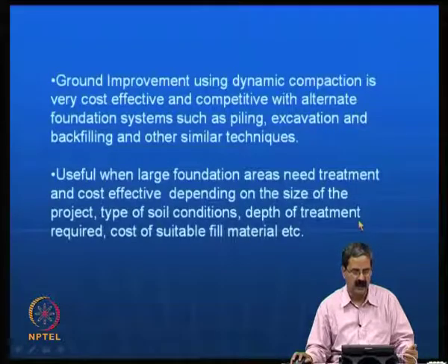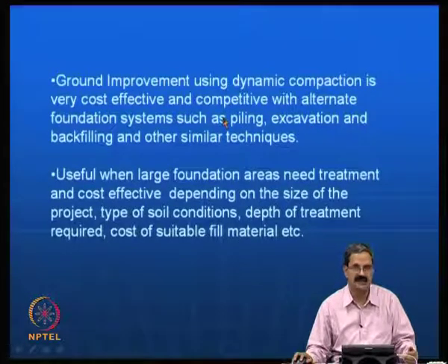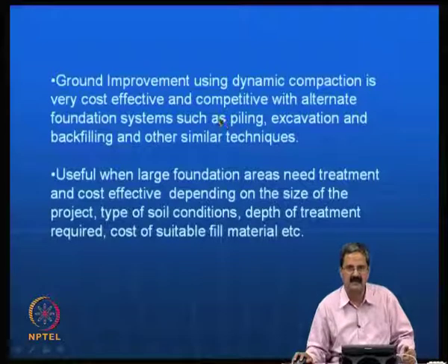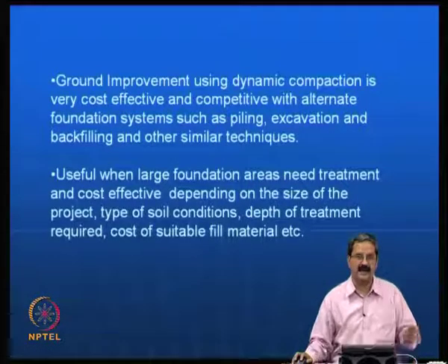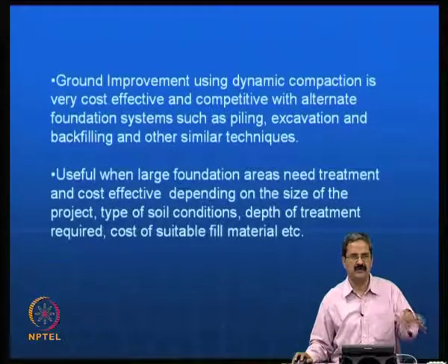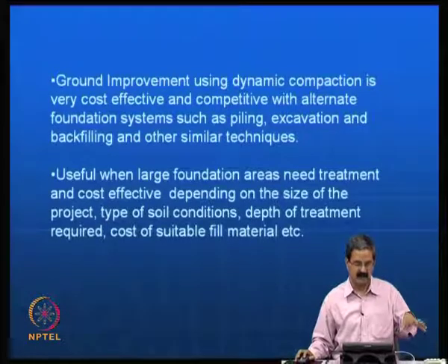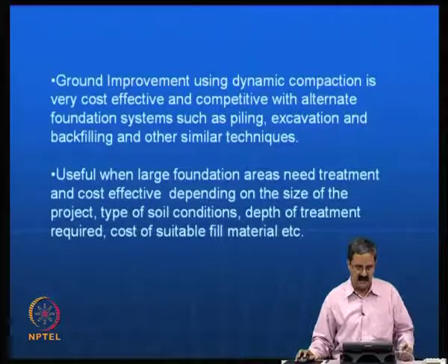That was what I meant, and particularly these people have explored a lot of other options in the site, like other similar treatments, like removing the whole soil and backfilling, and some of them trying to do piling. So, for example, if you want to increase the bearing capacity of the foundation area, why do you not go for piles, why do you go for just simple compaction which we do not know much about. So, it depends on the consultant that the project has. If somebody is a geotechnical consultant, he will be able to give geotechnical alternatives, but if there is a structural consultant, maybe he may recommend piles because he has a lot of confidence.